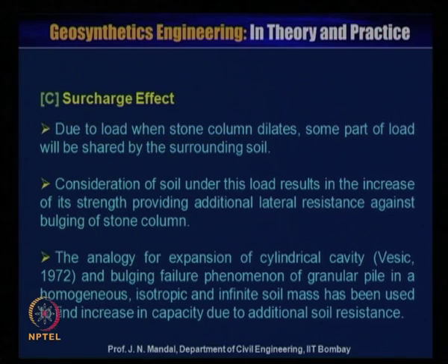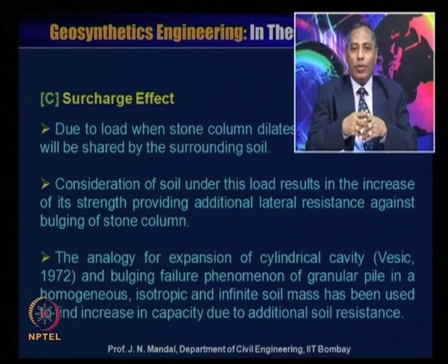Next, surcharge effect. Due to load, when the stone column dilates, some part of the load will be shared by the surrounding soil. Consideration of soil under this load results in an increase of its strength, providing additional lateral resistance against the bulging of the stone column.